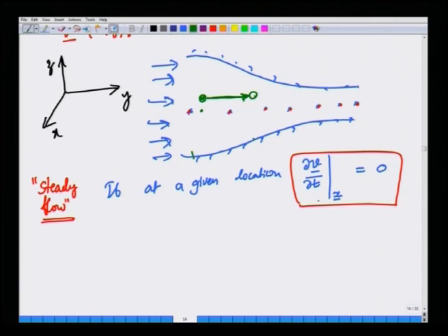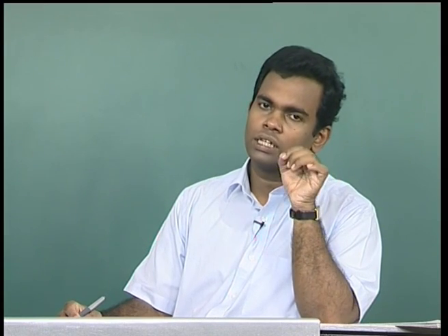So, this is what we mean by the convected contribution to the substantial derivative. Even if the flow is locally steady, that is steady in the Eulerian sense, a given fluid particle can acquire acceleration or deceleration by virtue of moving from regions of higher velocity to lower velocity, or lower velocity to higher velocity.